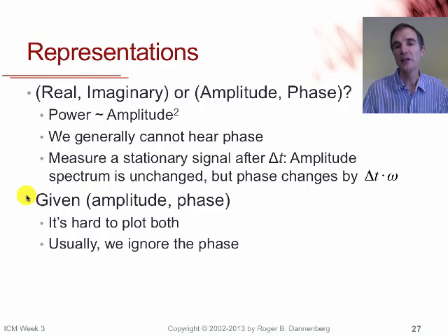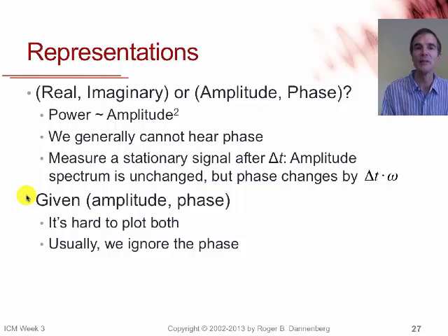If you measure a signal and then you measure it again at some time difference, delta t, the amplitude spectrum is unchanged, but the phase is going to change by delta t times omega, the frequency. And so, the fact that the amplitude does not change with time delay is maybe the reason that we're so sensitive to amplitude and we kind of ignore phase, because these time differences are all kind of relative.